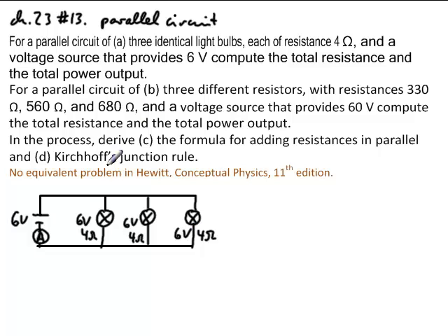So as the total current is flowing through here, part of it will go this way, part of it will go this way, part of it will go this way, and all three of these here are added up to be the total current, which is what the next thing says. The total current in the circuit equals the sum of the currents in its parallel branches. The sum equals the current in the battery or other voltage source.